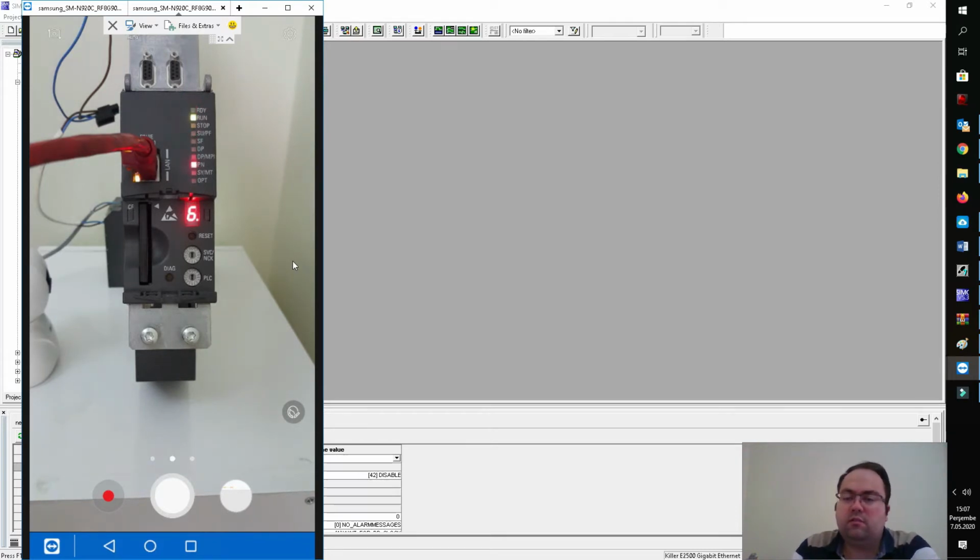If there is something wrong during the startup phase, then you get stuck at some other point. 6 means the system is started and our CPU is ready to download and operate. All the communication ports are available. In our case, if you see the number 8, that means a fan failure.